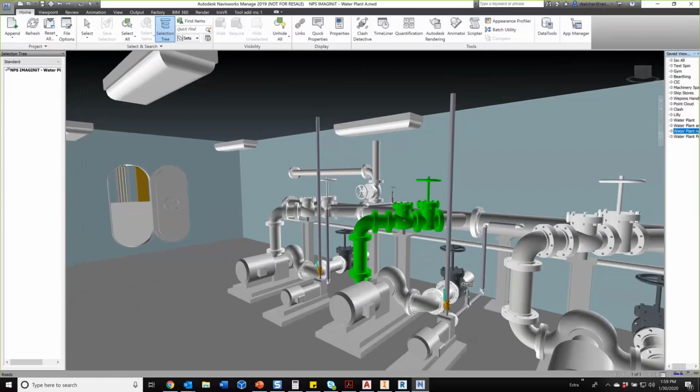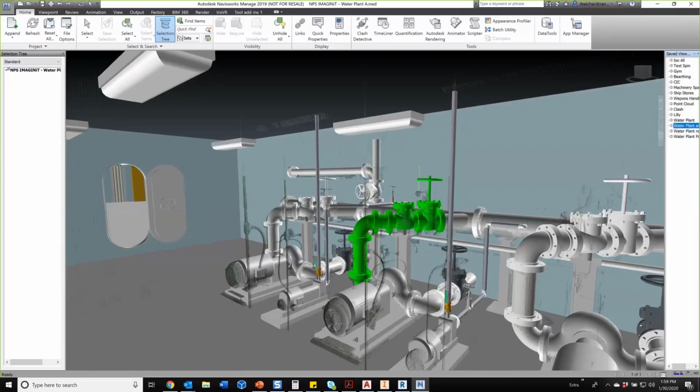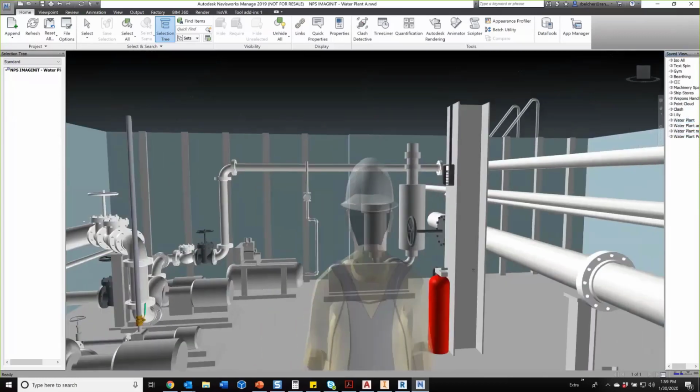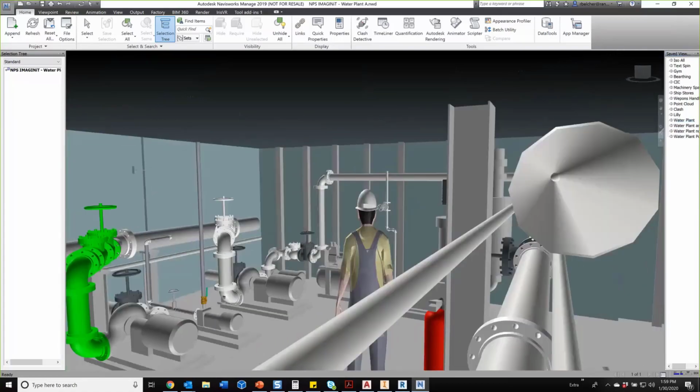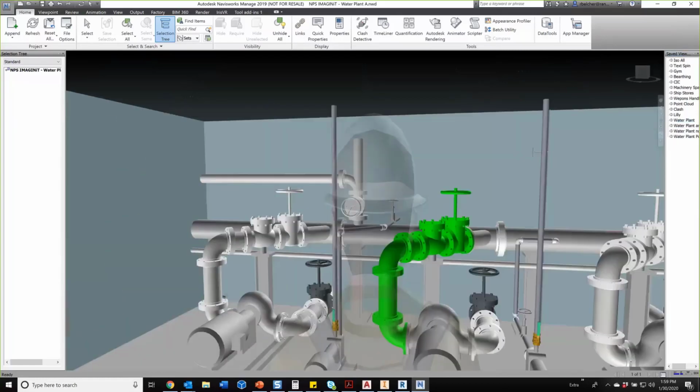I did this all in Inventor. I used the pipe routing tools inside of Inventor to basically trace the pipe runs with Inventor's piping components. There's both of them together. And then here is inside of Navisworks, a full-scale character going through and looking at the data.